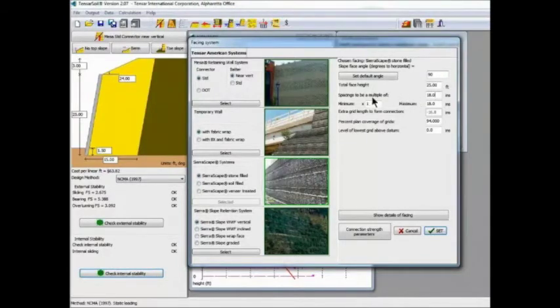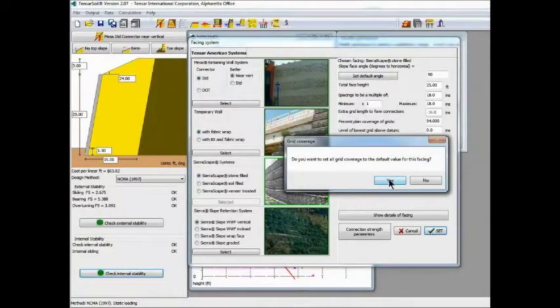You'll see that the spacings of the geogrid are now set to be a multiple of 18 inches, and that's because the basket height is 18 inches. So we will have some difference in the geogrid layout. Also, 94% plan coverage of the geogrids is used because SierraScape system typically uses two widths of UX HDPE geogrid side by side over the basket width. So we have 94%, which is our standard. And when we're ready to progress, select Set and click Yes,